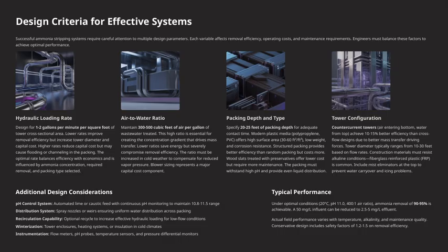If we operate at lower ratios, we save energy but risk severely compromising the removal efficiency. Also, in cold weather, we need to increase this ratio to compensate for reduced vapor pressure. Keep in mind, blower sizing, which impacts this ratio, is a significant capital cost.